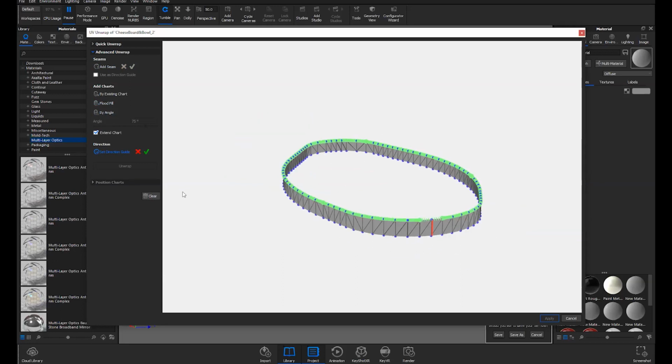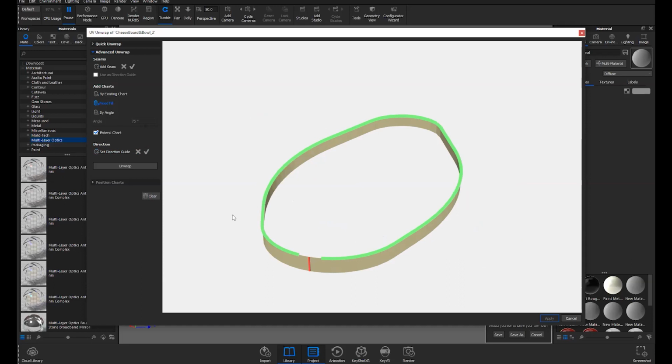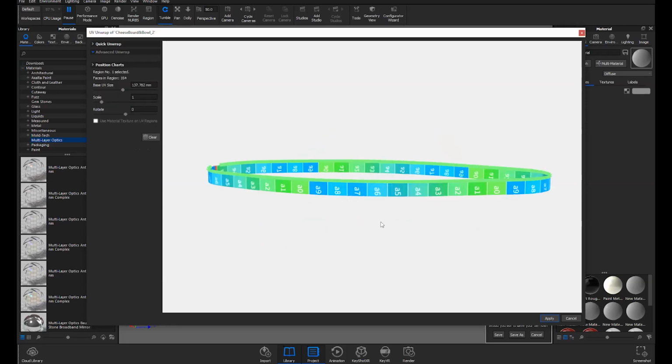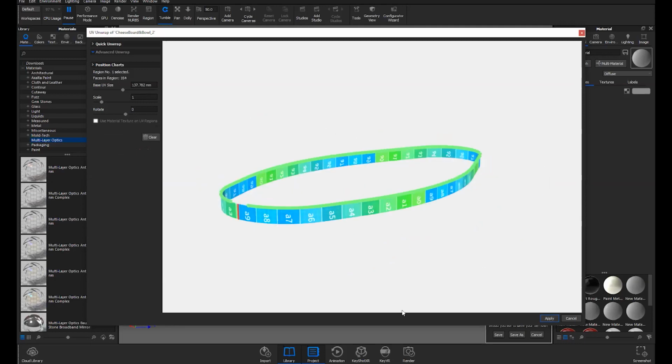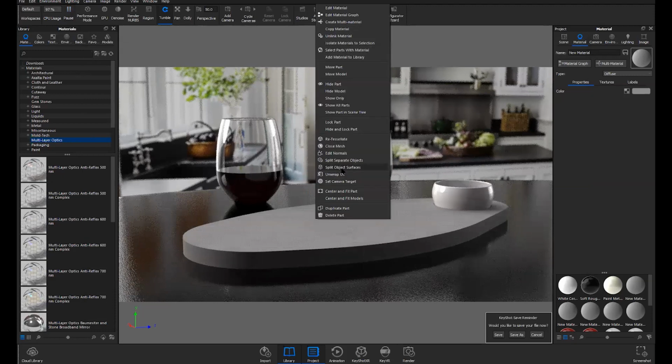And then once I'm done, I hit the check mark, and then I can select by flood filling. You see how flood fill is selected? I can flood fill the part that's going to be UV unwrapped. And then from this point, I can unwrap, and you can see the UVs have been mapped in the manner that I'd like them to. I can apply that, and then now we have a UV wrapped correctly piece around the side. So that's essentially what UV unwrapping is. You do something similar to the front. Let me unwrap UV again.